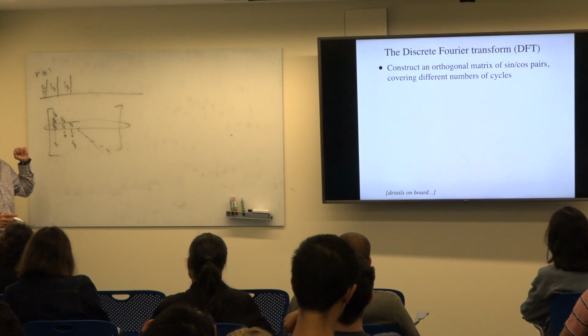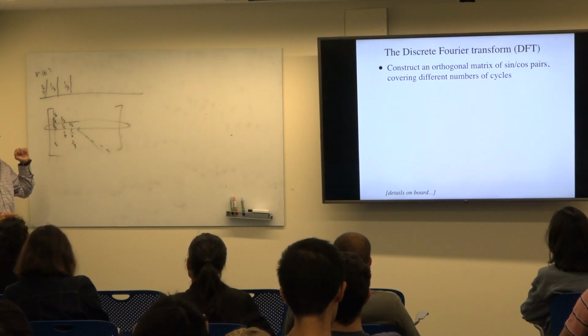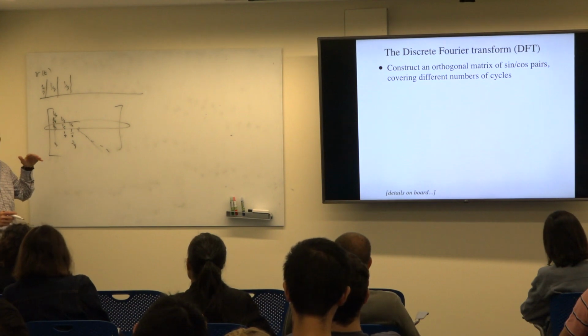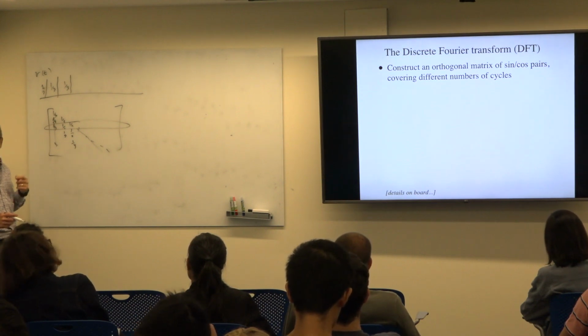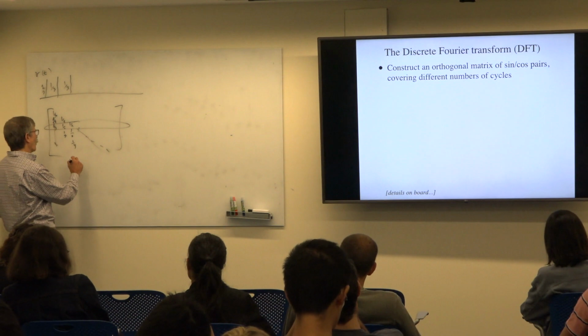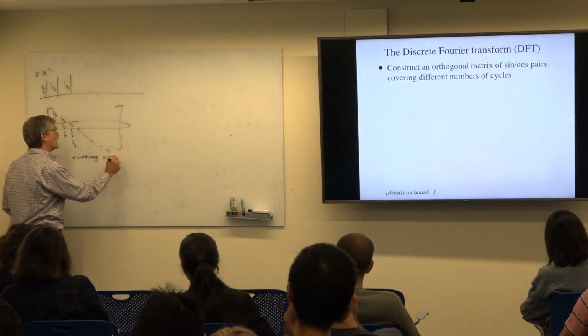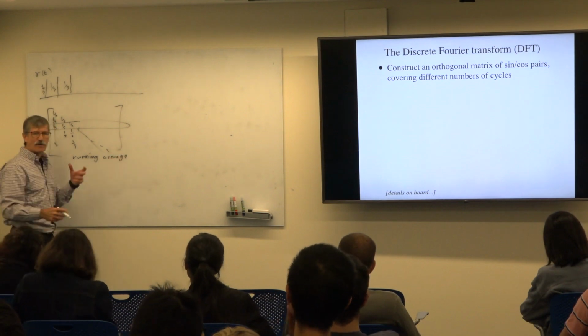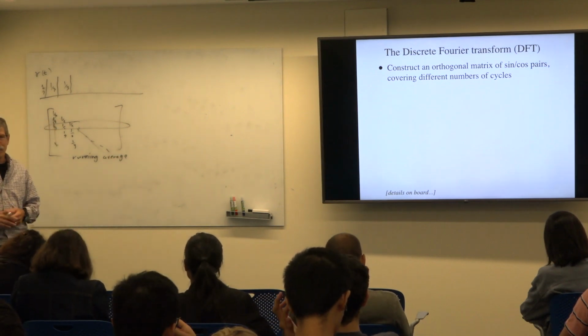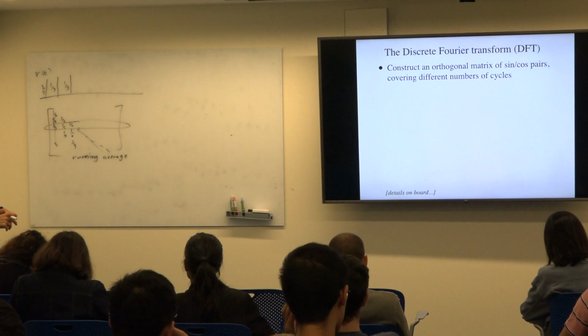The output at time 4 is an average of the input at times 4, 3, and 2. The output at time 15 is an average of the input at times 15, 14, and 13. It's usually called a running average because it's an average that's running over the input, and each time it's an average of the recent past. Okay? That's a good example.